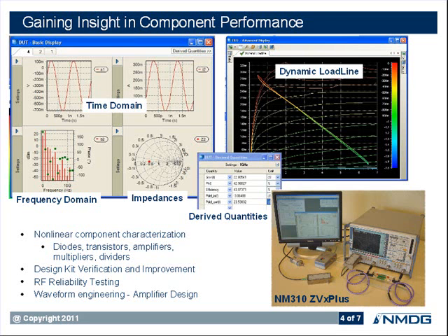And because with this incremental investment, you do have the voltage and the current waveforms both at the input and the output of the device under test, you can actually measure and represent impedances both at the input and the output of your device under test, which is very convenient for optimal matching of transistors in your amplifier design.